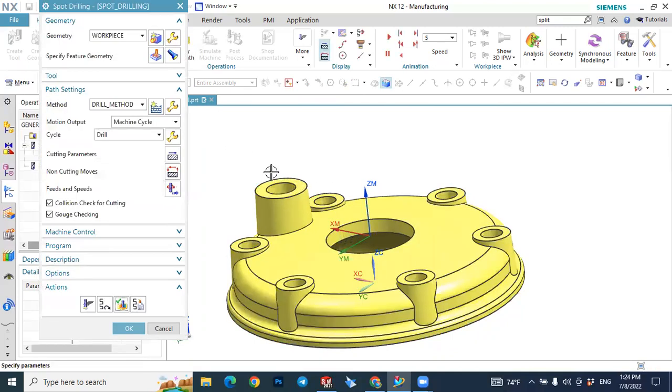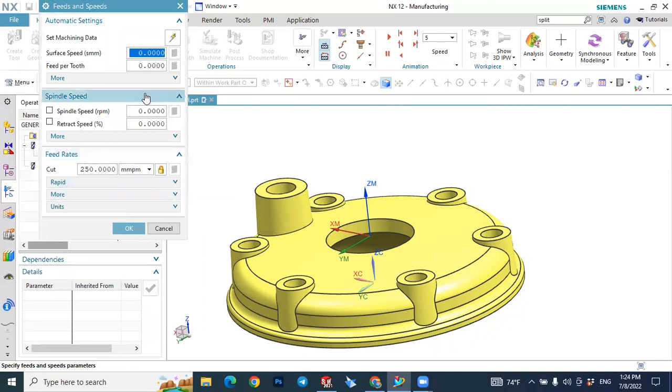And here we can define the cutting speed and the feed rates of the tool. So you can write here the speed, for example, 1000. It depends on the tool specification, so it will be given in the tool specification, and according to the tool specification in the tool library you will define this one, and if you just press calculate, these parameters for the machine will be calculated.